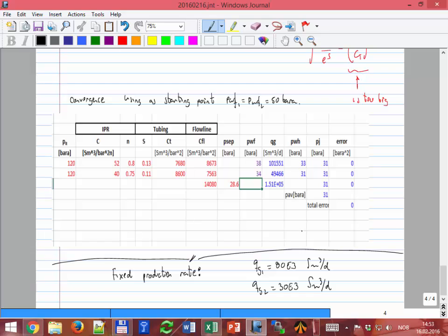One thing that is important to note is that when you don't have any controllable element, any equipment that you can change, the solution is unique. Okay, this is what the system is going to produce, period. Doesn't matter if the reservoir engineer puts in some holy water and they improve it somehow, doesn't matter. That's what the system is going to give you. You're bounded by that. Now if you come and you say I have chokes, I can regulate, or I have pumps, or I have a compressor, then that's a different story. Then I can get any other combination of rate.